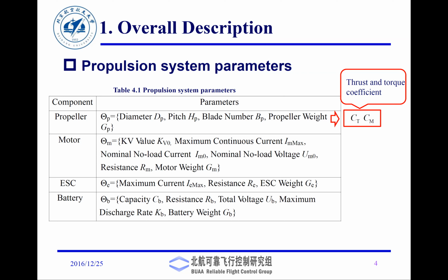So when we study the prop dynamics, we are going to take into account something called the blade element theory. If you take a small strip of this prop, it becomes like a blade. As this blade is swinging through the air, it's like slicing the air. The prop would have a leading edge and a trailing edge. The leading edge is basically the edge that is going to slice. You would realize the trailing edge is not sharp, so it will be dull. You can run your thumb along it like this.